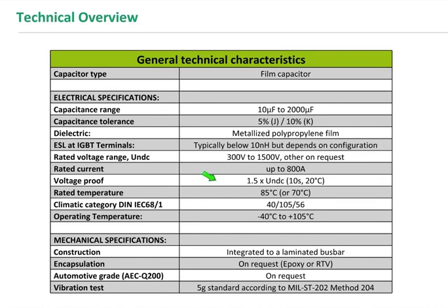In our production, each time we are testing the cap link. How are we doing it? We are testing, of course, the capacitance, also the loss factor, also the insulation resistance, but also quite important for you is that we're also doing an overvoltage proof test. Here we are testing the whole capacitor bank at 1.5 times the rated voltage of the capacitor, during 10 seconds at room temperature, or what we say at 20 degrees.